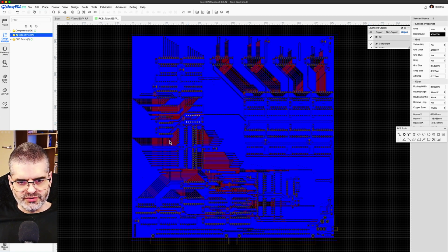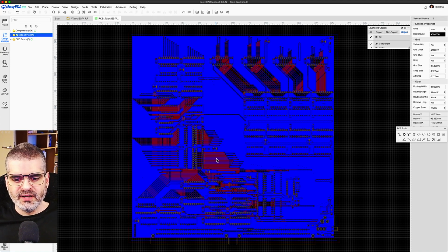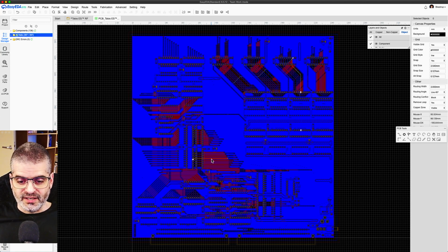You also notice that most of the time I don't let the copper fill go in between lines that are close together, because I don't have a ground plane to stitch the copper fill in between these lines. And if I don't stitch them, they actually can contribute to more cross-coupling as opposed to reducing cross-coupling, because at the wavelength of the higher harmonics in the circuit, at the speed of light, it would just take too long to actually reach ground potential.